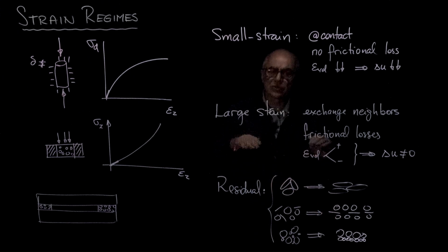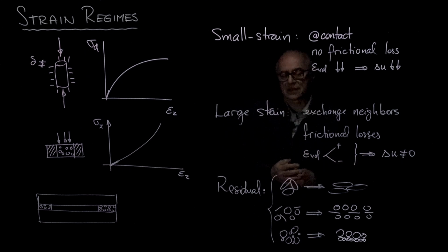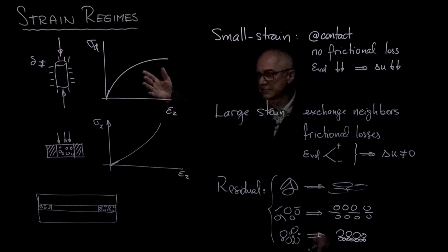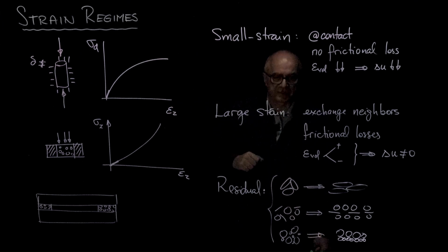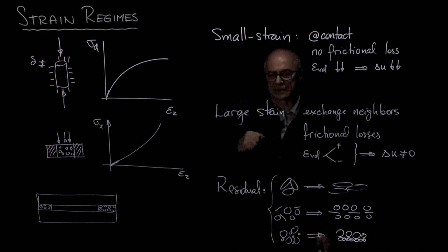So when do we draw the line for what is critical state? Typically, because we run those tests in a triaxial cell and it's limited to 15% deformation, or we could go to 20% deformation, we go to that point and maybe we extrapolate a little bit more to infer critical state, but actually it is a procedural definition.